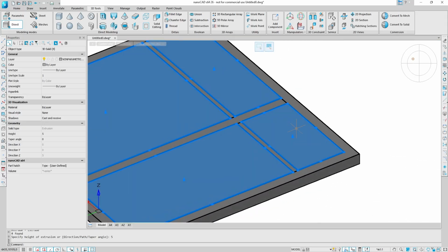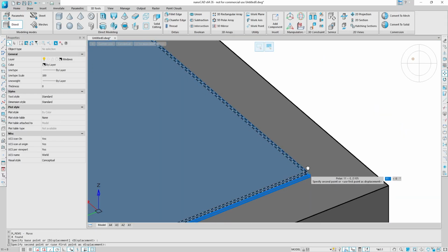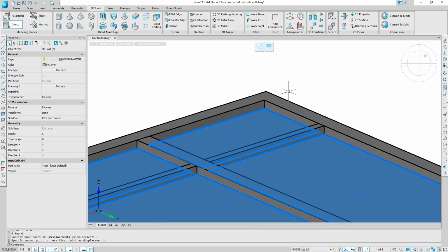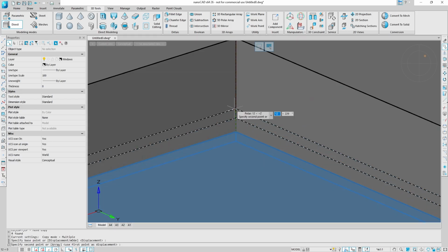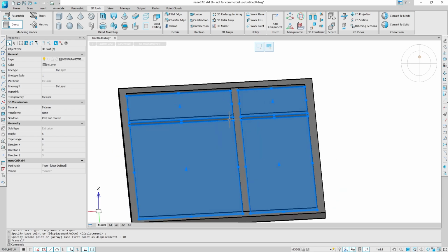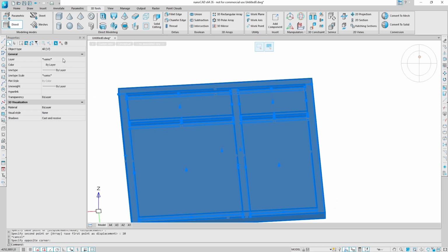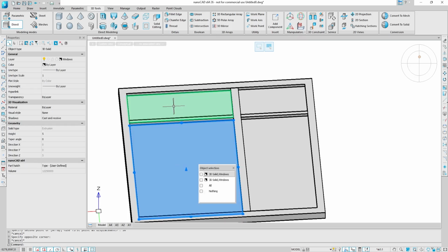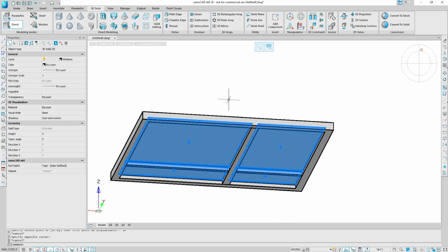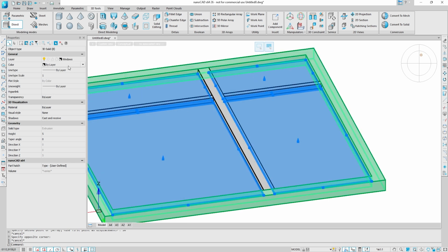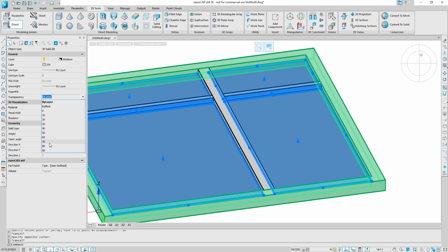Select 4 panes and lower them to the middle of the frame. Move a copy of the glass at a distance of 10 mm to make a double-glazed unit. Transfer all the built solid objects to the windows layer. Use the Properties panel to set the glass color with the number 254, transparency 70.